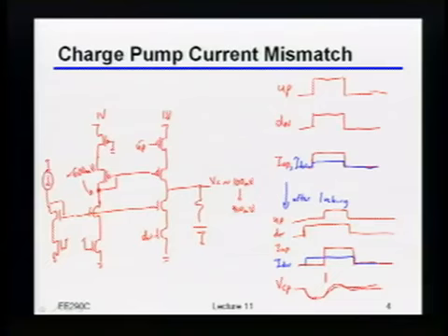So how is it different from getting the spurs at the output of the phase detector? Okay, so the trick is that, in the phase detector, we did talk about last time how it too was always making the updates on a reference clock. But remember, those movements had to do with just noise being in the system.